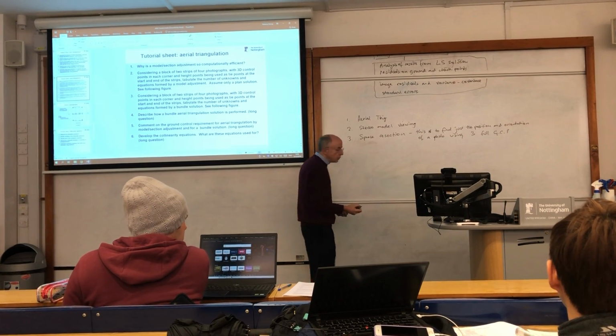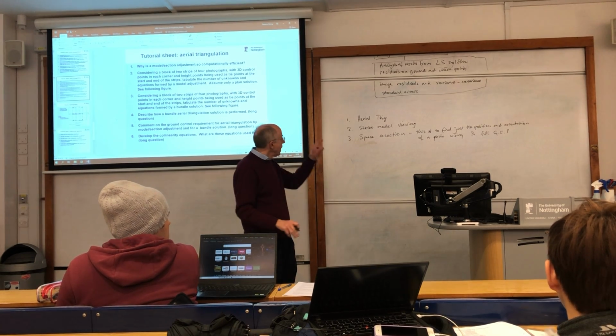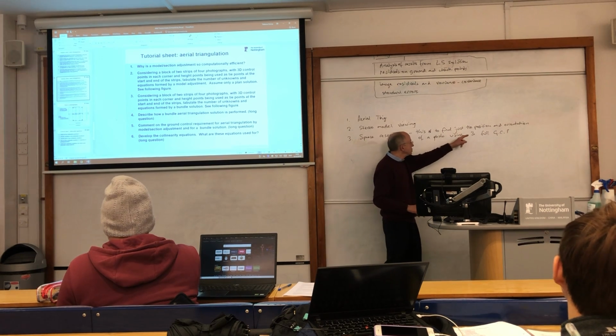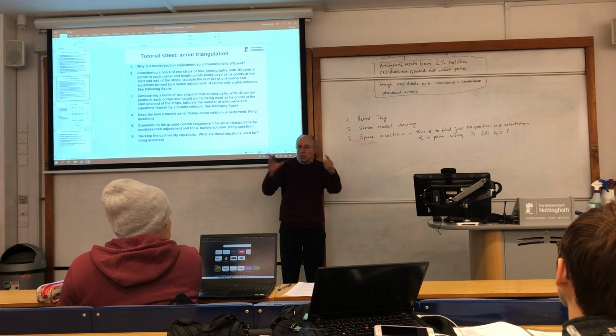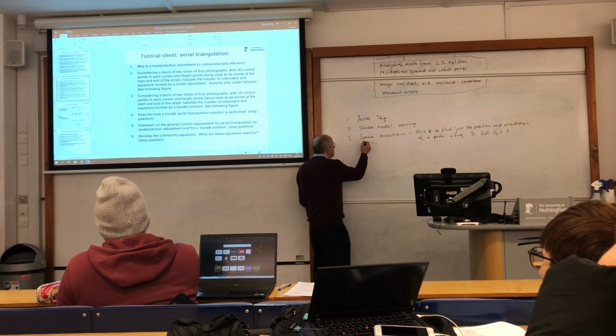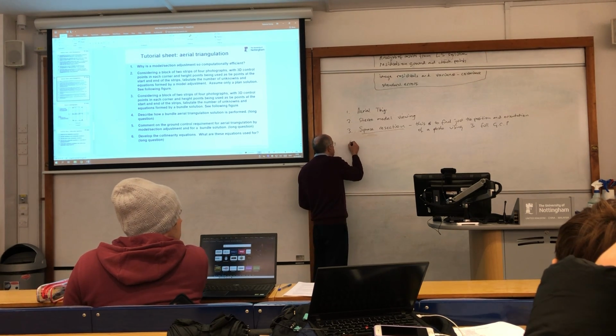So in other words, we know the coordinates of 3 points on the ground, X, Y and Z, and we want to know the position where the photograph was taken and its orientation. Not a bundle adjustment, not an aerial triangulation, just a single photograph to find its position and attitude, and that's called a special name, space resection.